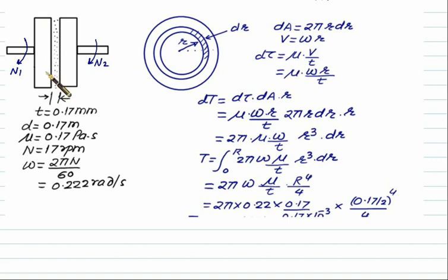So if you see the front view of this one, you will get one plate, and the second plate will just overlap here. But the problem in this case is that as the distance from the axis changes, the linear velocity for all these points will also change. Angular velocity will remain the same, but the linear velocity will change. So whenever the linear velocity changes, we'll take the concept of integration. For this purpose, we'll consider one elemental ring of radius equal to r, thickness equal to dr.